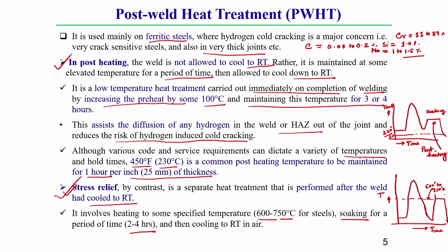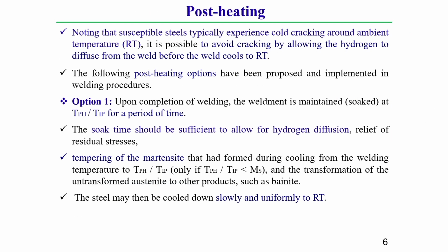And this holding or soaking time here is generally around 2 to 4 hours. After that, generally we cool down to room temperature. This you should keep in mind. This is generally called stress relief operation. Now, in detail about post heating and stress relief post oil heat treatment, I will discuss in the subsequent slide.